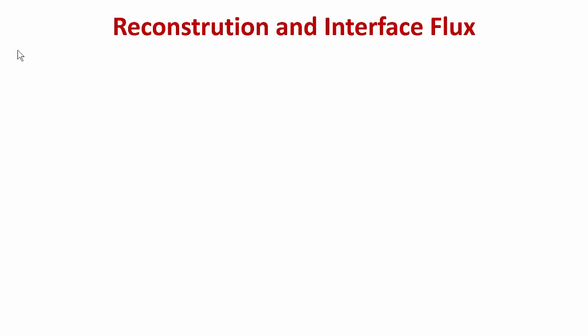So today I'm going to cover what you need to solve finite volume problems in 2D. I'm also going to start talking about systems of conservation laws and how to do the equivalent of a good enough scheme for systems of conservation laws. With how to solve problems in 2D and how to deal with systems of conservation laws, you can start implementing first order schemes for Euler equations, which is the first part of the project.